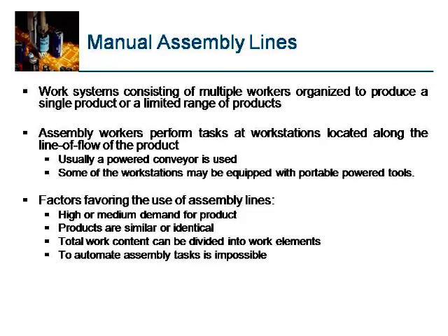When it is pushed with that force, it moves to the next station, and in the next station the base part is stopped and again parts are added and it is pushed to the next station. Like that assembly is done. These are all typical characteristics of manual assembly lines.